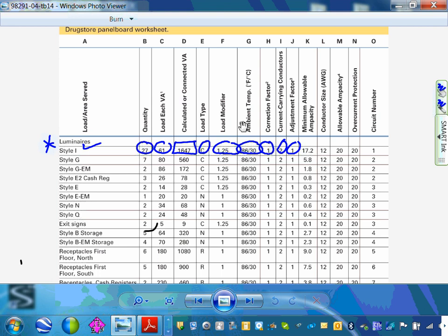Please. Which 310.15(B)(3)(a) is it, or (B) something? Go back one, the one at the top. Yep. Read the table. Okay, now, suppose there were 5. Then instead of 1 here, what do you put? 0.8. Okay? Makes sense? If there were 5. I'll tell you what you do with it in a second. Then, minimum allowable ampacity.